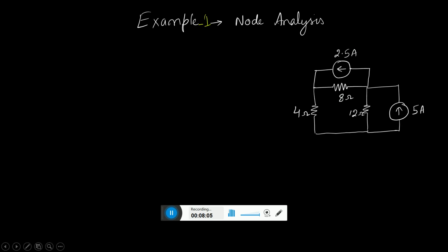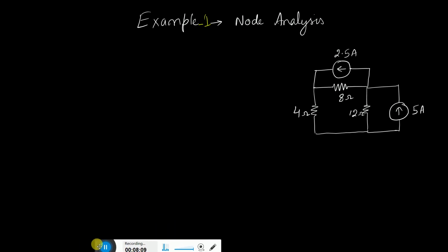So let us take an example and try to solve that. In this example, let us find out how to solve this equation. So here let us choose that in this problem we have 2 nodes, so many nodes. Let us choose one of the nodes here and say it 1 and another node over here, and let us say this is 2. And V1 is obviously the node voltage V1 and V2 is obviously the node voltage V2. And another node we will choose and we will make it the reference node, and the potential over here is 0 because this node is a common node of all these 3 elements. So we can take the reference any one of the 3, but the other 2 we need to mark as 1 and 2.